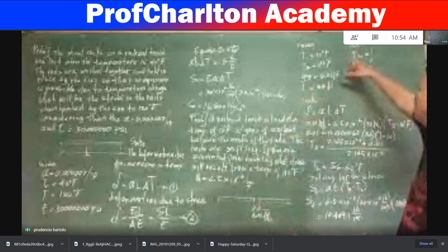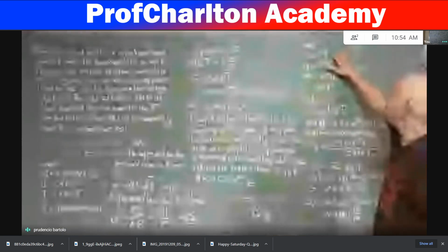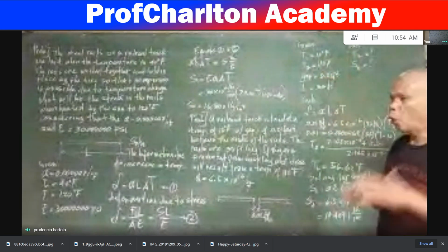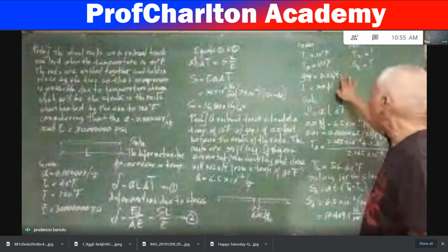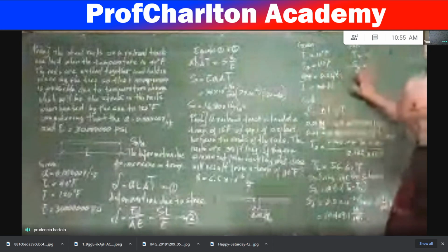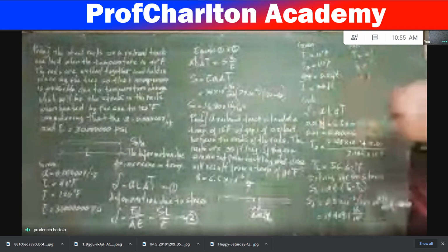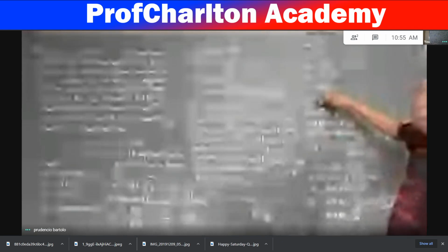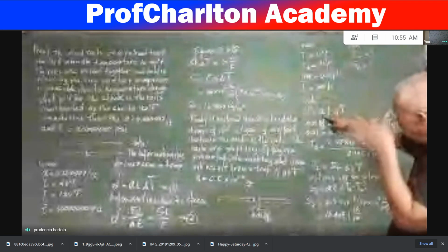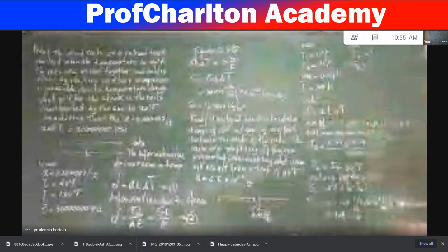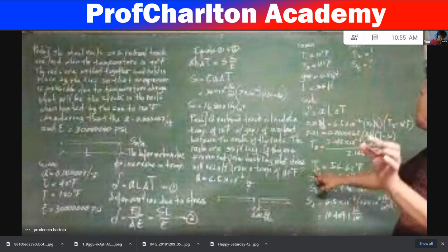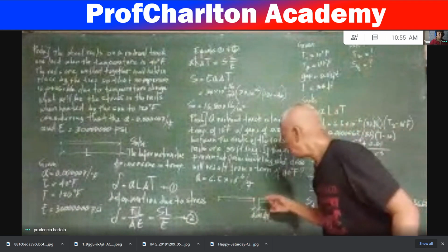So therefore, we have here the given data: T1 equal to 10 degrees Fahrenheit, T3 that will be 110 degrees Fahrenheit, a gap of 0.01 or deformation for each rail of 0.01 feet. The length is 33 feet. We are asked to find T sub 2 and whether stress develops. So solving for the thermal deformation, deformation is equal to the coefficient of thermal expansion, the length, the change in temperature, to find T sub 2, that is the temperature when the two rails meet.